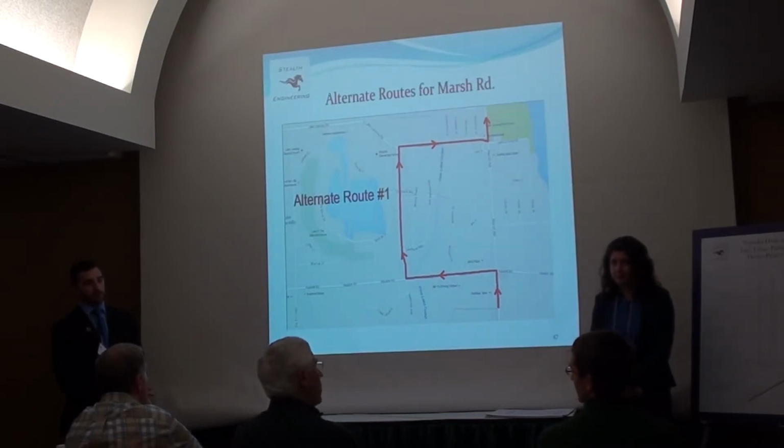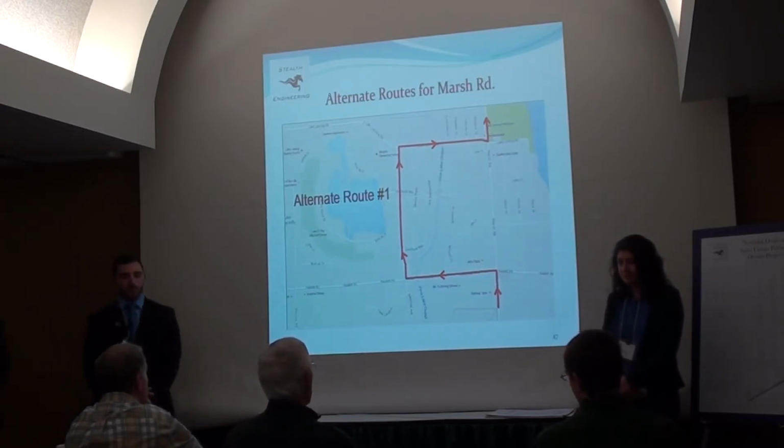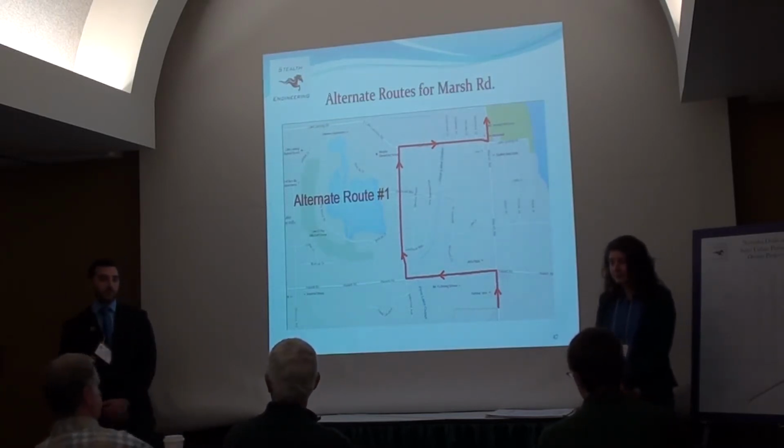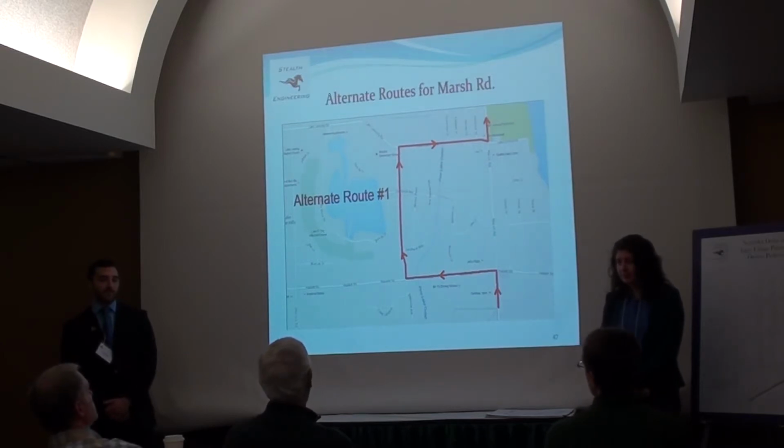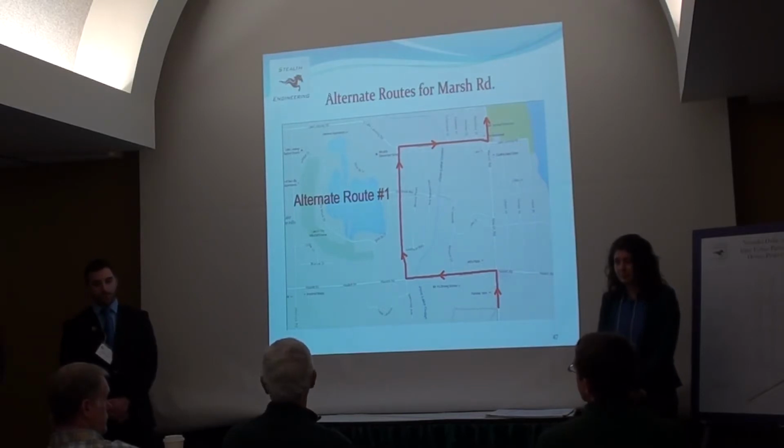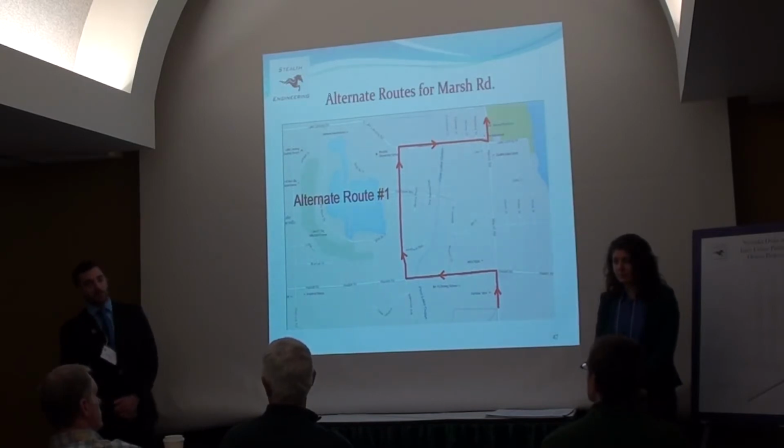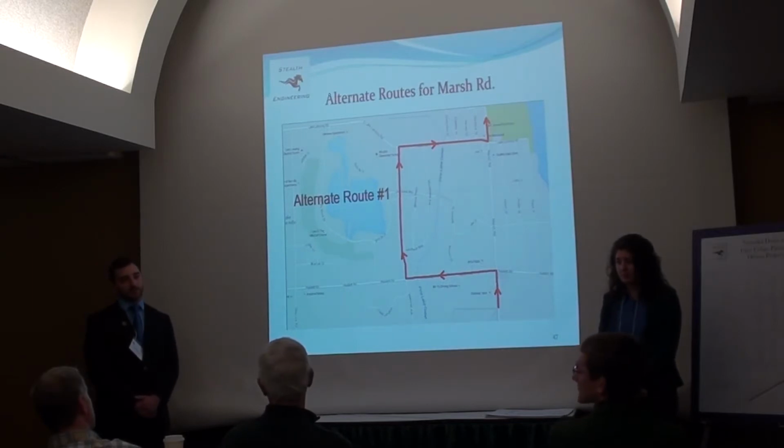Okay, I'm Dave Love. I work with the Grand Commissioner's Office, so I'm pretty familiar with this area. I'm intrigued by your idea of the bike path, and I think that's probably a good idea. One of the things that happens is sometimes you wind up cutting off existing drainage patterns, and I didn't see that you've taken into consideration drainage under or through the trail at all. Is there any consideration for that, like swales on each side?